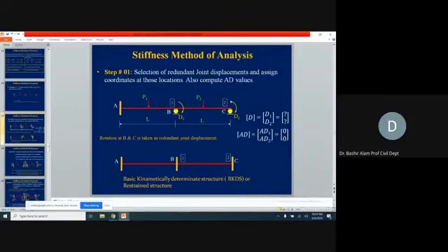The moment at C was in the counterclockwise direction and it was 1 kip-foot. So AD2 will become our -1 now. Why minus? Because it was opposite to this D2. D2 was in clockwise and this is in the counterclockwise direction. But here as we don't have that condition, so we put this equal to 0.